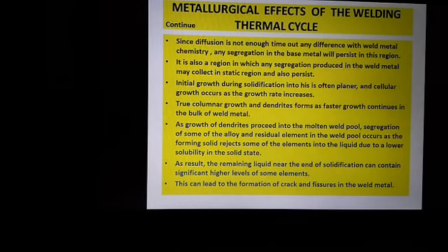As growth of dendrites proceeds into the molten weld pool, segregation of some of the alloy and residual elements in the weld pool occurs as the forming solid rejects some of the elements into the liquid due to their lower solubility in the solid state. As a result, the remaining liquid near the end of solidification can contain significantly higher levels of some elements.